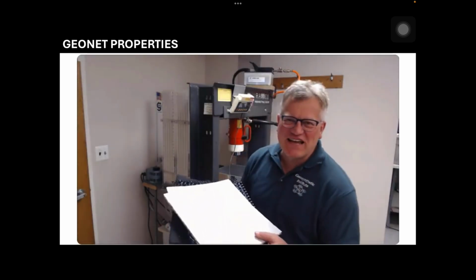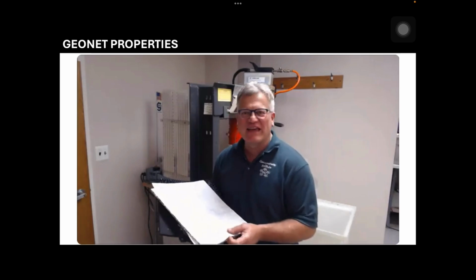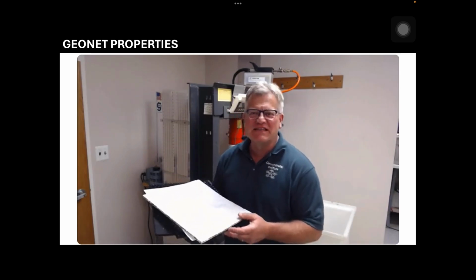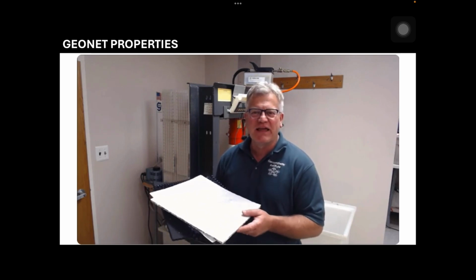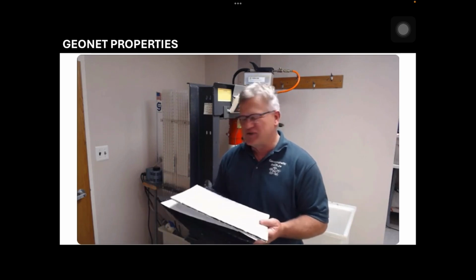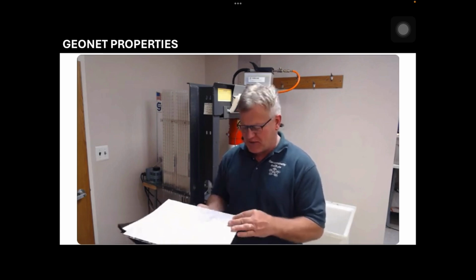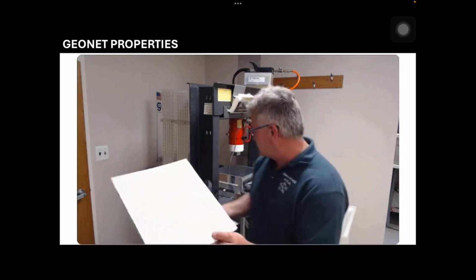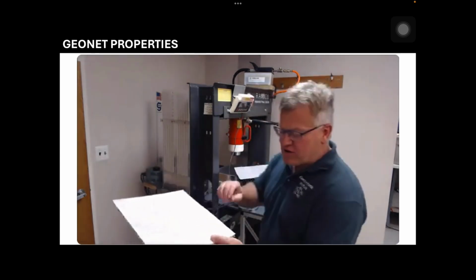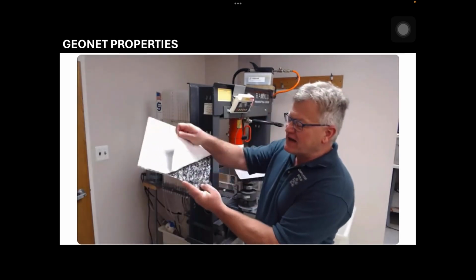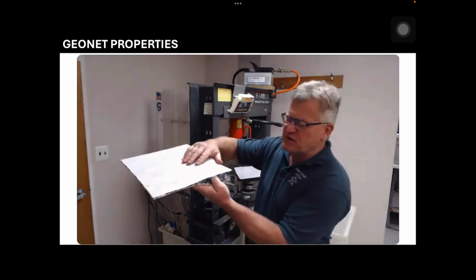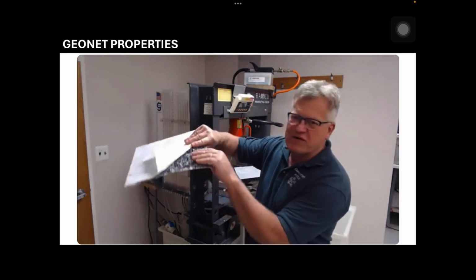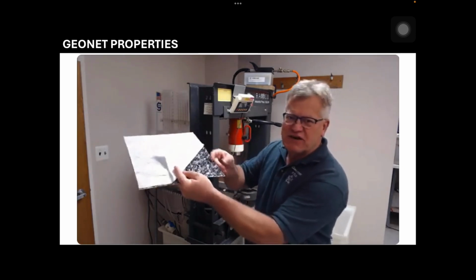Hi, we're here at the Geosynthetic Institute in Folsom, Pennsylvania. Take a look at ASTM D4716 for transmissivity and in-plane flow characteristics of geocomposites, geonets, geospacers. These materials typically consist of a core and a textile. The textile is typically bonded to the core. The textile is used as a filter. The core, or the spacer, is used for transmission.